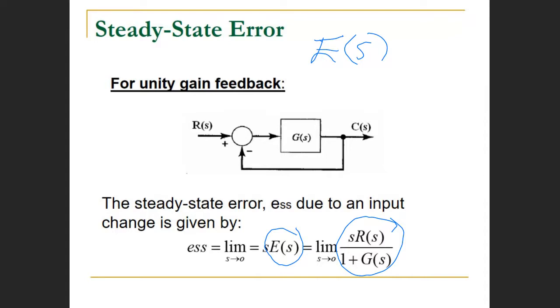All right, remember, what I believe you're now proposing is the block reduction technique, and what that technique is going to do is to close this entire thing here into a box where the input is R of S, output is C of S. But what we really want is to find out what E of S as a function will look like.